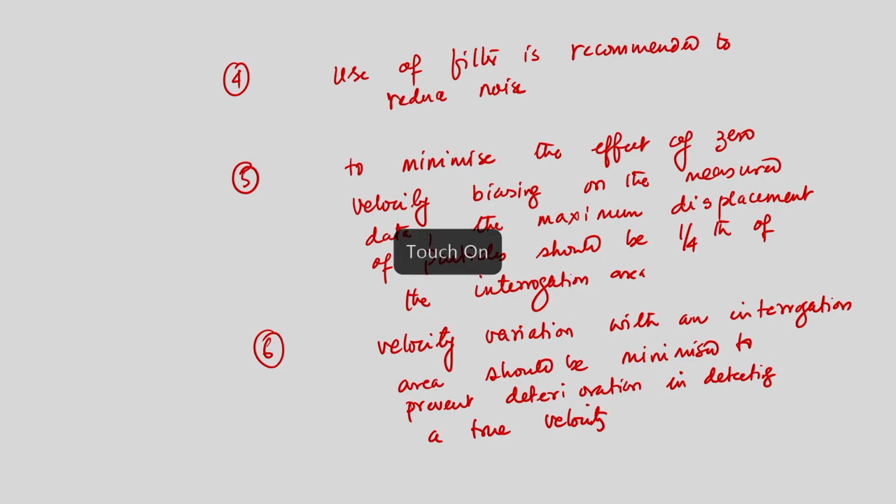Now finally, if we try to recall, one important point in the context of this technique is that we are using a light source. We are illuminating a particular zone in the flow field using a laser light, capturing two different images, and from there we correlate the displacement of particles which are seeded to the flow. We know the time between two consecutive images captured by the camera, and from there we will predict the velocity of the fluid.